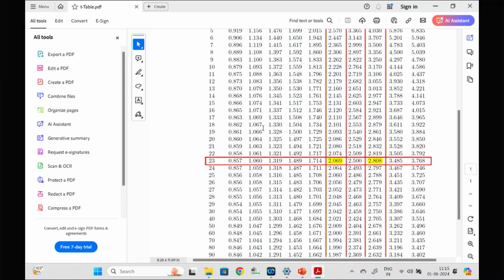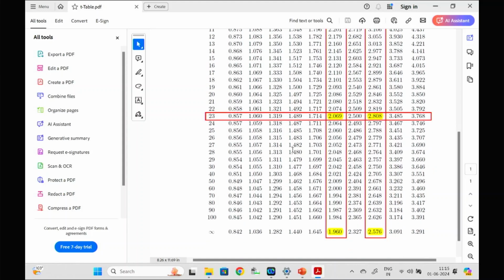And as I have mentioned, for other types of material where the variability is different and the accuracy required is different, in all those cases we can go on taking different degrees of freedom, with a different number of sample specimens, and for, say, 60 degrees of freedom we can get the t value for the 99 and 95% levels.